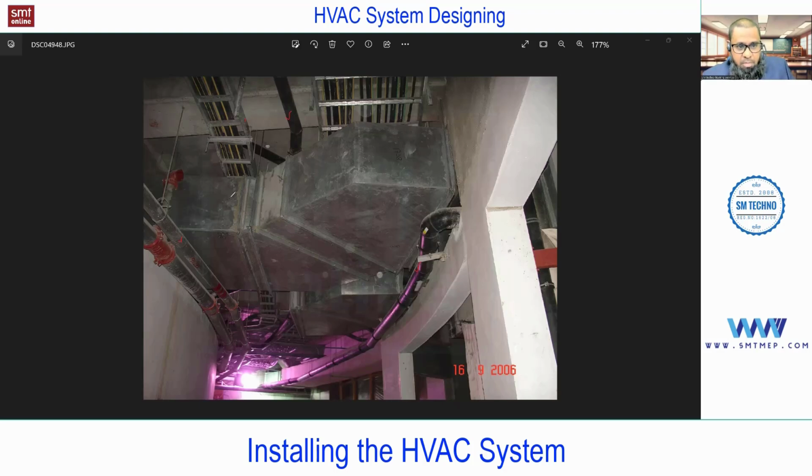So now we have an option for the duct. Remember, the height of the duct we decide as per the available clearance, considering the clearance required for other services. This is very important. As an HVAC design engineer, this point, as I said, we'll discuss in chapter 6, point number 8, and it is related to duct designing. In duct designing, most commonly we use rectangular duct. It can be oval duct or round duct, each with advantages and disadvantages, but most commonly rectangular duct. Rectangular includes square; we are not calling square a separate category.